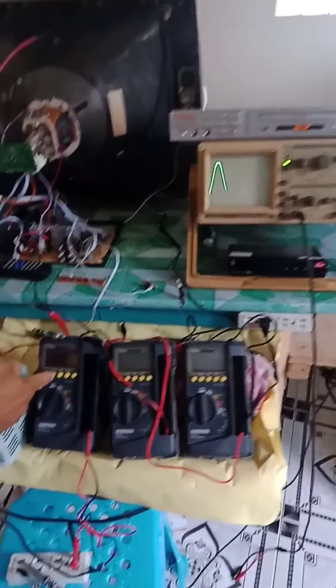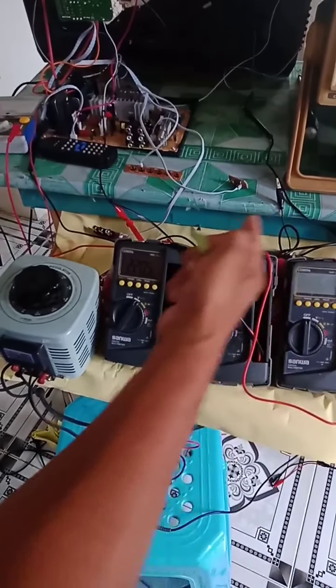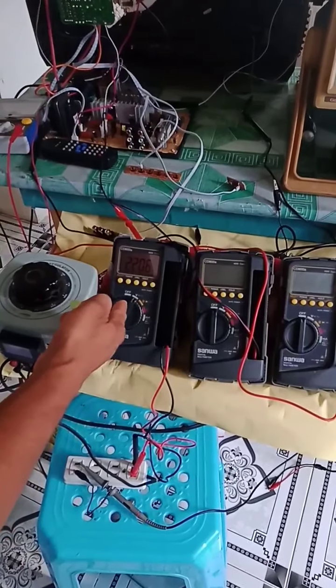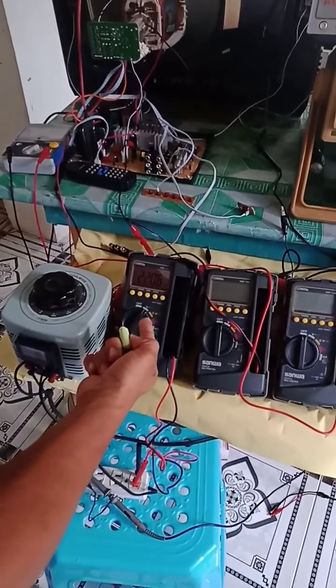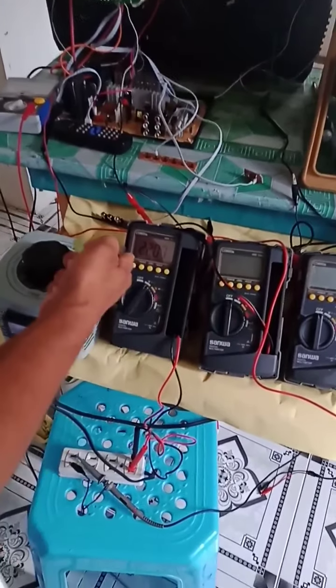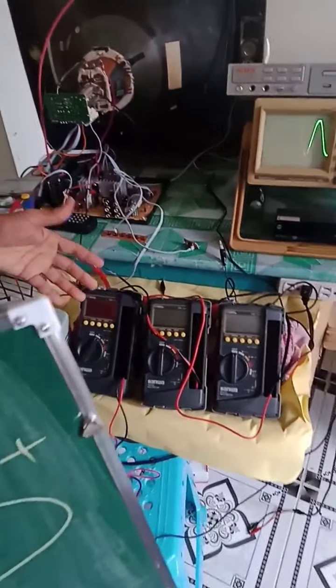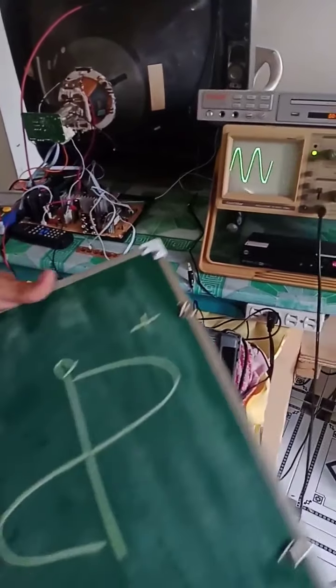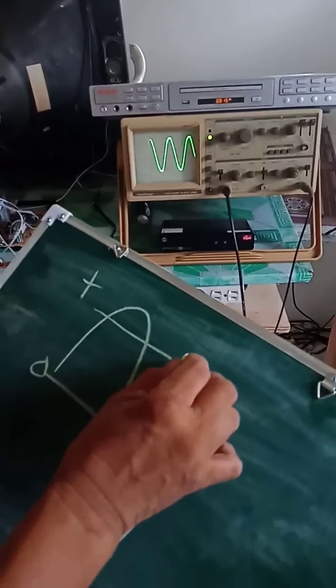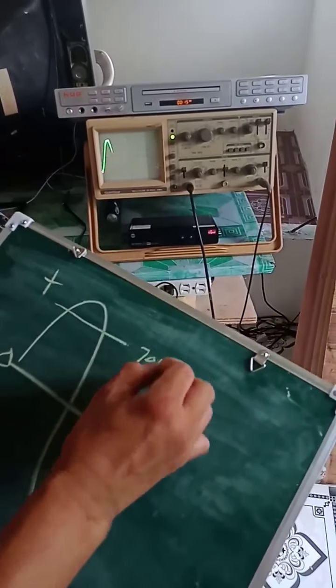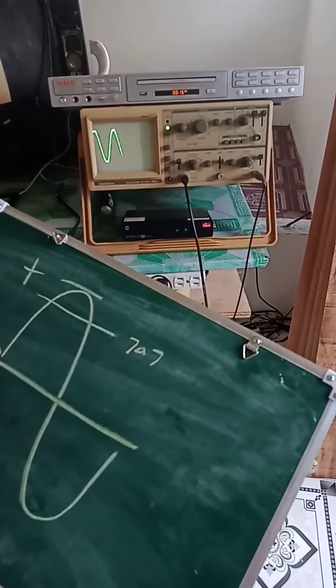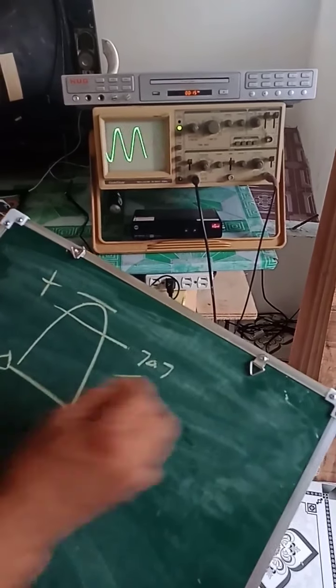The 220 volts, which is now at the outlet, we measured the voltage at the outlet, and it reads on the tester there. The tester registers 220 volts. That 220 volts is the measurable voltage by our tester, and it is actually the effective value. It is only 70.7% of the peak value of the amplitude.